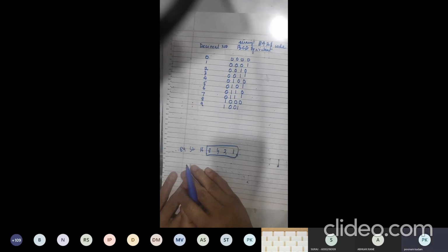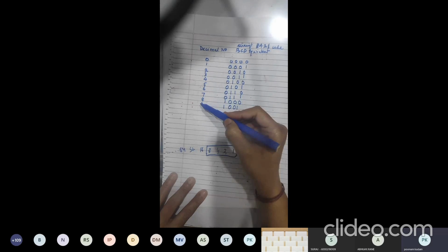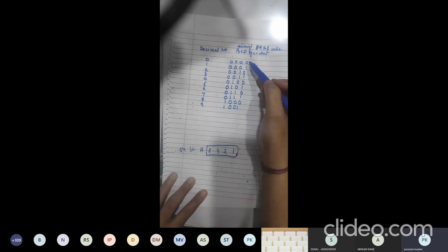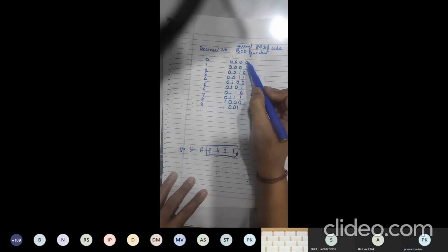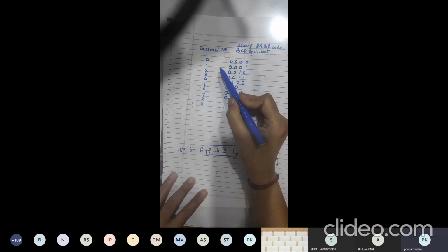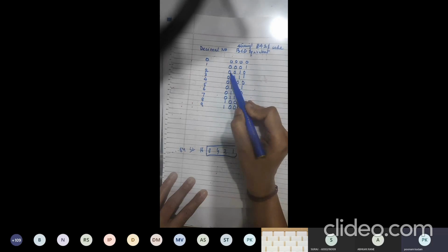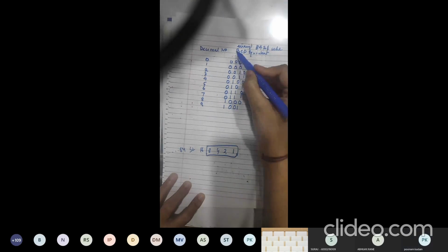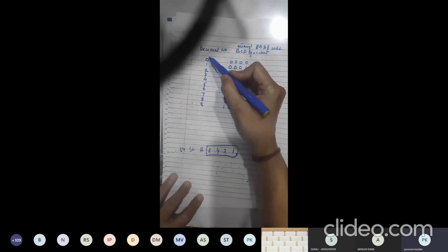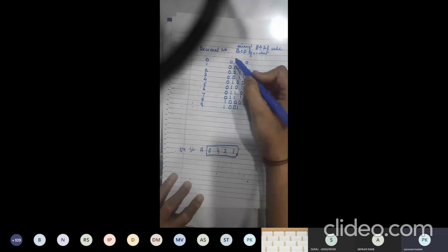So 8421 code means each of these decimal numbers from 0 through 9 is represented by its straight binary form. In binary also we write 0 as 0, 0, 0, 0 in 4-bit representation. The binary equivalent for decimal number 1 is 1, which in 4-bit will be 0, 0, 0, 1. 2 is 0, 0, 1, 0, 3 is 0, 0, 1, 1. I suppose this is clear. So in BCD code, these 10 symbols, 0 through 9, are uniquely represented by the corresponding 4-bit binary equivalent.